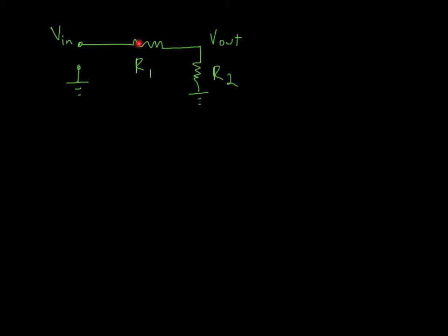All right, so this is I, and that's I as well. So there's no junction. Even though I've drawn the circuit like this, and I want you to start getting used to the way this looks, remember, these lines are connected. There's no junction. These are two resistors in series. What makes it just maybe different is we're interested at the corner here between the resistors, what the voltage is. All right. So I is the same through this whole circuit, and so therefore we can write I. Oh, let me choose a different color here.